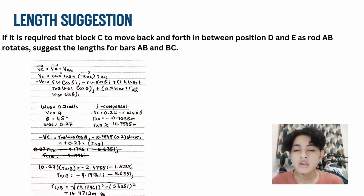So here we want to calculate the suitable length for block C to move back and forth. The first step is we have to use the velocity equation. First, velocity of block C, Vc, equals velocity of B plus velocity of B with respect to C. So velocity equals omega times R. Then we take the numbers which we get from the diagram.